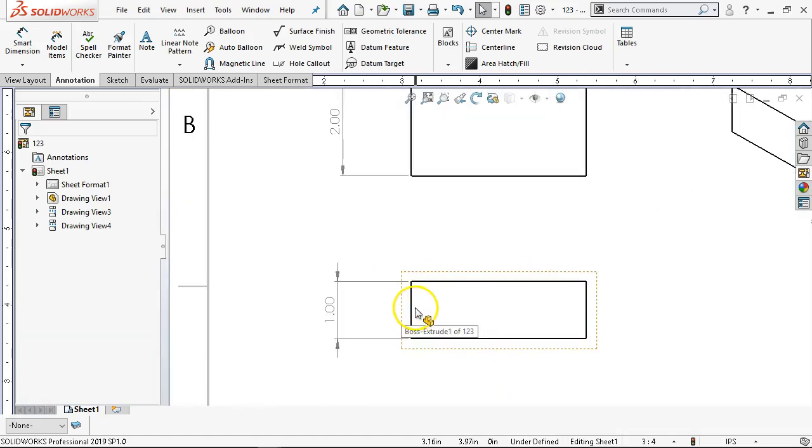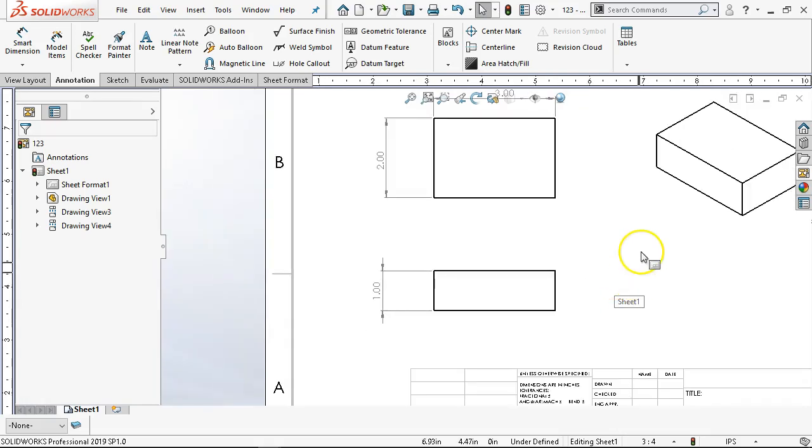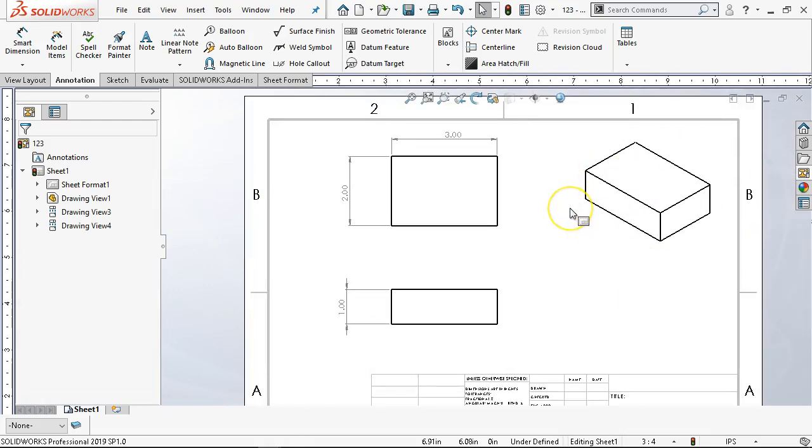conditions. Now, the flatness, the parallel, establishing datums and going further into it, we're saying we don't need to control that, and so we're not going to come back on an inspection and all of a sudden start talking about flatness when the part is 1 inch plus or minus 5. Whatever angles or geometry is being produced, we're going to live within that, because this is our legal document. This is our production document, what we want made.